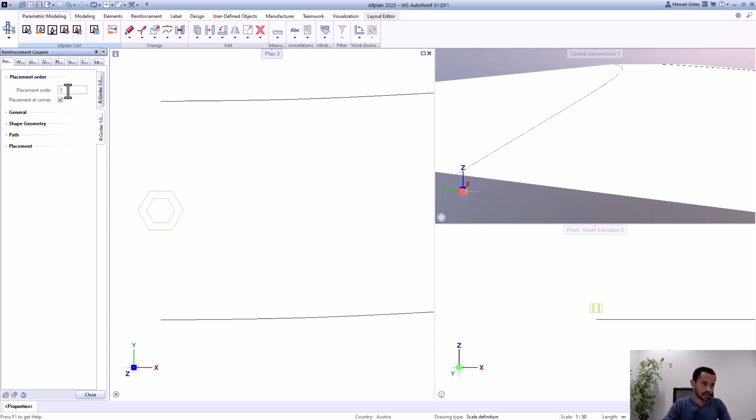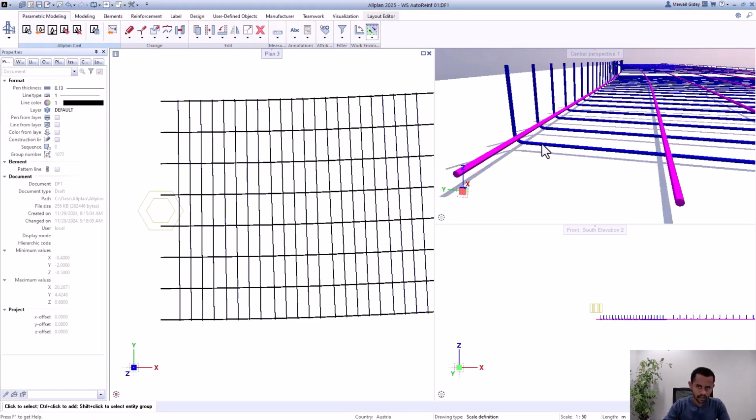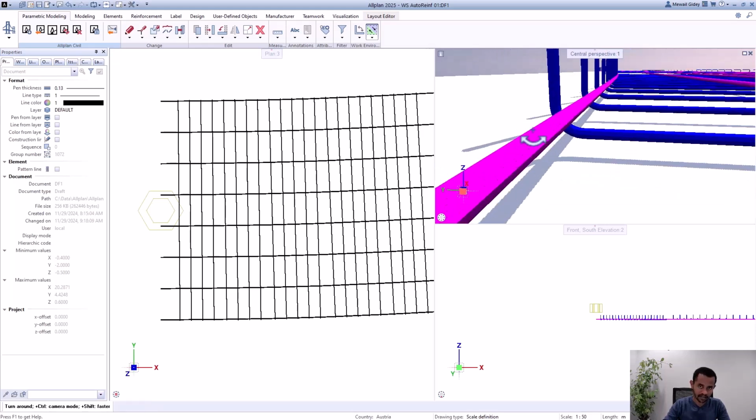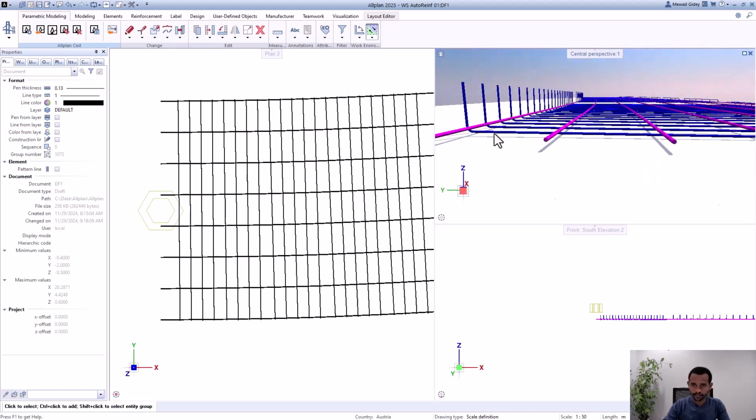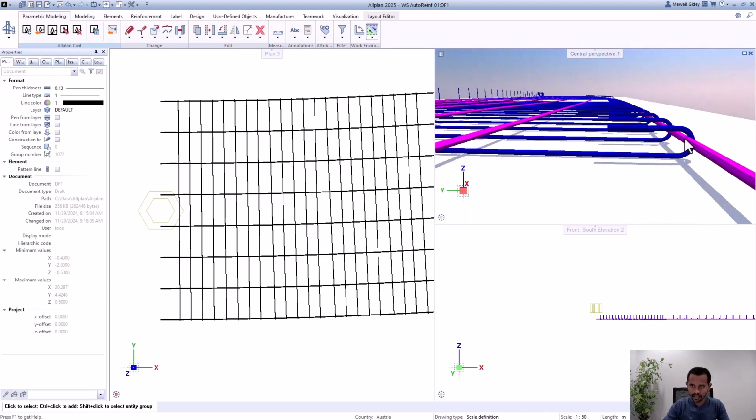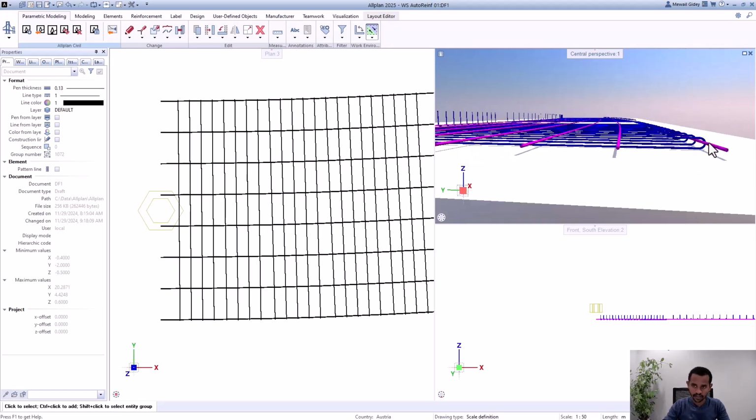And if I put a value of -1, so I could have a list of property sets, if I put a value of -1 here, it means place at the last. I wanted this property set to be placed at the very end. Now it doesn't matter if I put 1, -1, or 10, because this is going to be placed after the longitudinal ones. If I press close after my placement, you can see we have placed it here, the corner like shown. And these are all moved all the way to the center. Here you can also see it's moved all the way to the center.